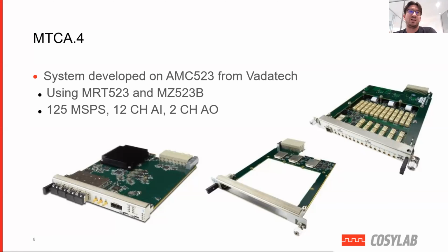The main reasoning behind MicroTCA.4 is, of course, its abundant support from vendors like Vadatech and Struck, and a large selection of existing boards on the market. Of course, performance is a big reason as well, and support for advanced features like remote crate management through IPMI. In order to test the system, we use boards from Vadatech. You can see them on the slide.